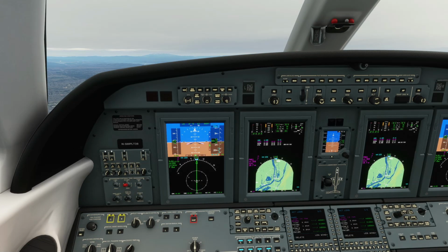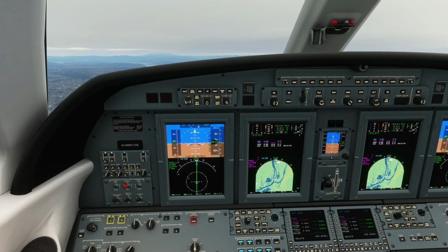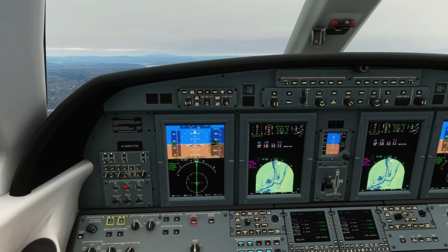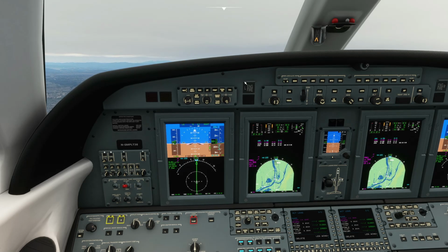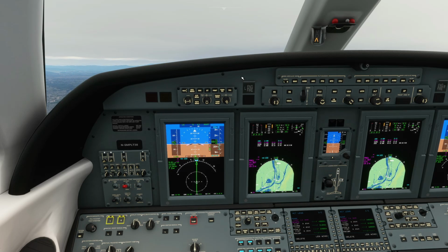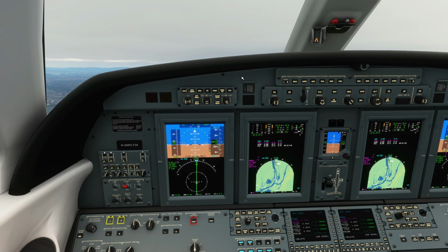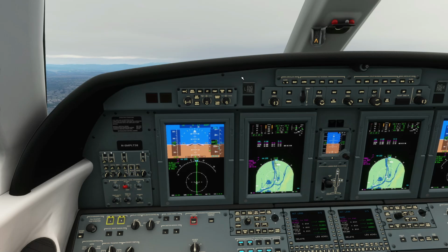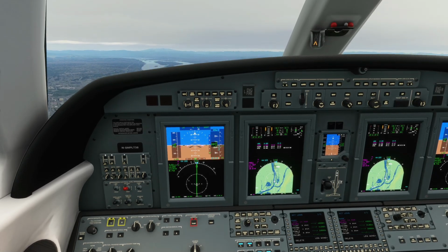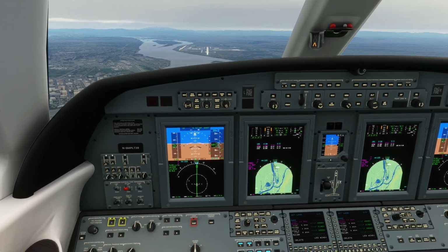Oh guys, we might have to take control here. Extend the speed brakes, slow us down, get rid of the autopilot, because looks like we missed the glide slope. And we will descend manually to pitch the aircraft for descent until we get back on the track.